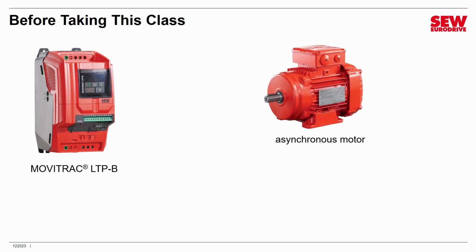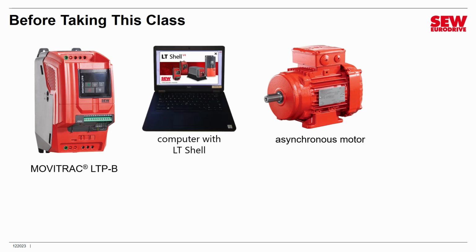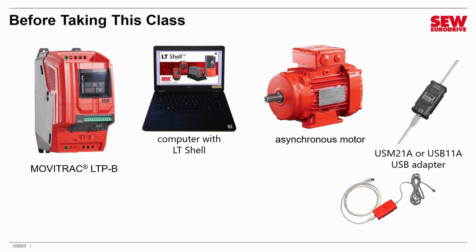You will need a small asynchronous motor. Any brand will do. You'll need a PC loaded with the LT Shell software, which you can download from SEW-EURODRIVE's website, and I'll show you in just a moment where to do that. You'll need the USM21A or USB11A USB adapter. This allows you to connect your computer to the MOVITRAC. The gray unit is the more recent USM21A, which is the current model. The USB11A is the orange one. It is discontinued, but it is still readily available in many facilities.